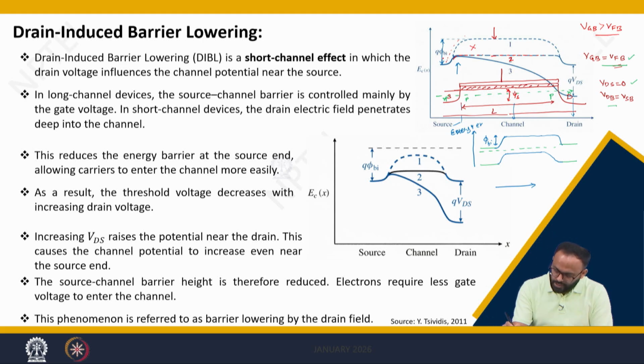So, the electrons which were available in the conduction band of the source can now easily move or diffuse towards the channel, but still, as there is no horizontal field coming from the drain, the current is 0, right. So, the electrons are here.